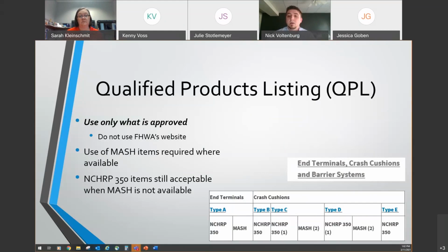We don't want to eliminate our options when we still need to protect something. An example of this is where we had a project that called for 6 matched crash cushions to be installed in 6 different locations, but the current approved matched crash cushion was actually not wide enough to protect the area. So this is kind of a limitation that we had discovered immediately.